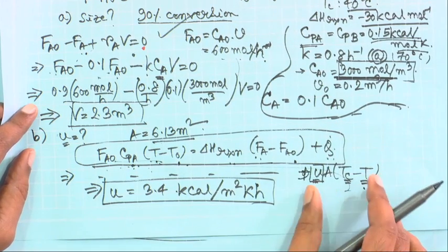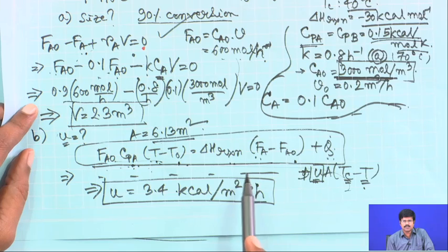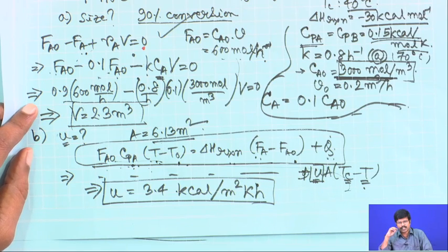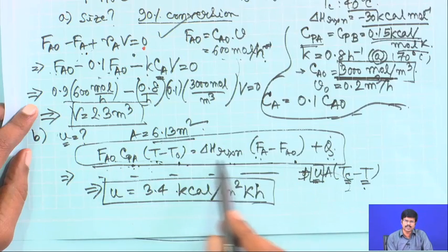So, q dot is basically this term. Now, if you have to directly plot say R t versus t, remember that when you are plotting your x versus t that you have got from the energy balance equation, that gives you an equivalent of R t versus t. But if you are asked to plot the rate of heat taken away as a function of reactor temperature, that is the R t versus t, or you are asked to plot G t versus t, that is the rate of heat generated as a function of temperature, you can directly go to this particular equation, the